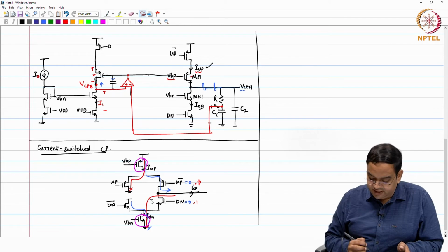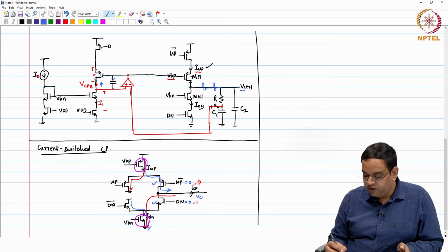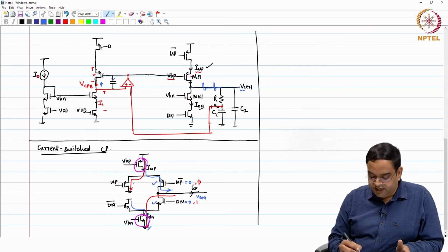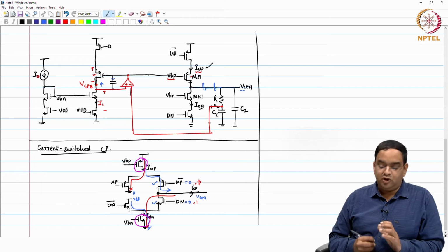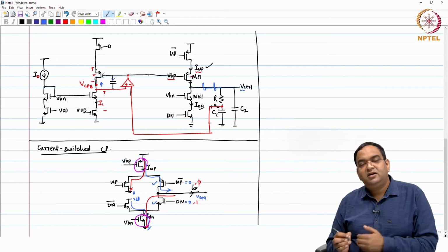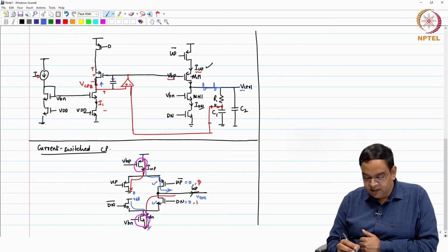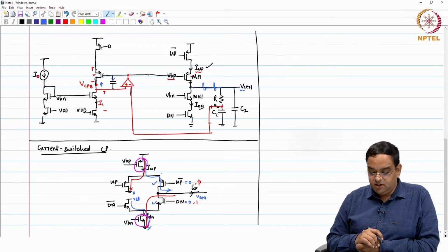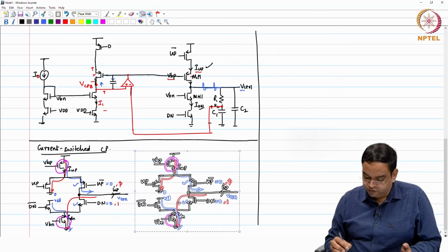This particular design has a problem that the switches which are operating, these two switches are actually having a V control at the output, whereas when you divert the current to the other direction, the one is ground, other is VDD. So, because of this, the exact current mirroring will not happen, or you will see additional current flowing in the charge pump output.